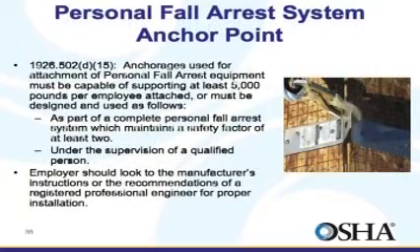Proper installation of the anchorage point is critical to the success of this system. It must be designed and installed to support the amount of force that would be applied to it if a worker fell. Consulting the manufacturer instructions or a registered professional engineer will ensure this critical component is properly installed and maintained.